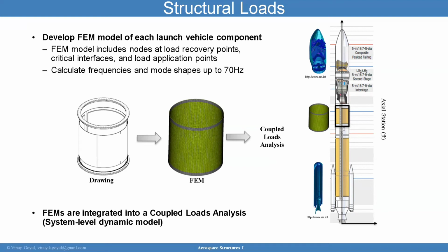So the finite elements are then integrated into coupled loads analysis, which is a system level dynamic analysis. Again, two types of models. One model is intended for a dynamic model. Another model is intended for stress analysis. So you'll take the drawing, right? Mesh it, so use finite elements, and then integrate into a coupled loads analysis, which will have all these components integrated into one system, including the spacecraft.